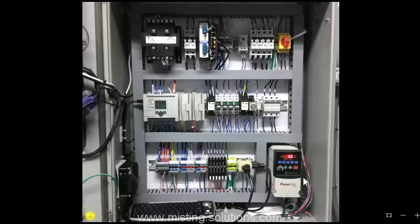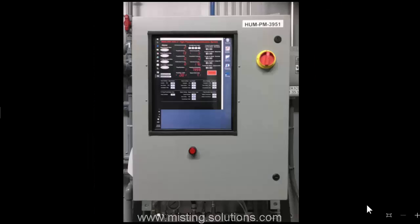There is a little light on each one of them telling you that they are on. And when they do come on, 24 volts AC power from this transformer goes into the top of each one of these relays, and then when it comes out the bottom, it actually goes to this set of fuse blocks here. Actually, it's the 4 fuses to the right side, here to here. The other 2 on the left-hand side, one of them is an input solenoid valve, and the other one is the bypass valve. So each solenoid valve, or sets of solenoid valves, is fused. And when each one of those solenoids comes on,